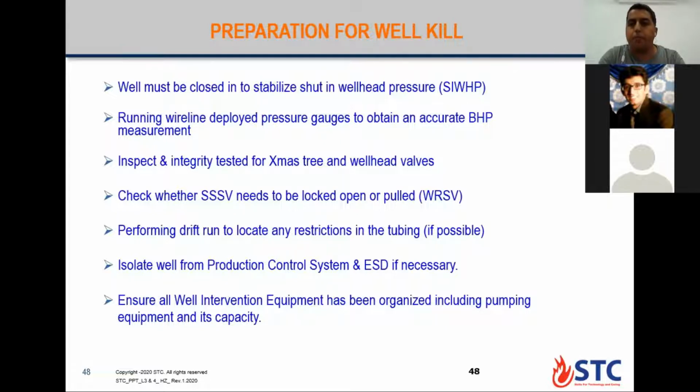Okay, what it means is we can close the lower master valve if we have a leakage in the killing valve or the flowing valve. Then we close the valve from the lower master valve, try to stabilize the wellhead pressure, and then open it to kill the well.